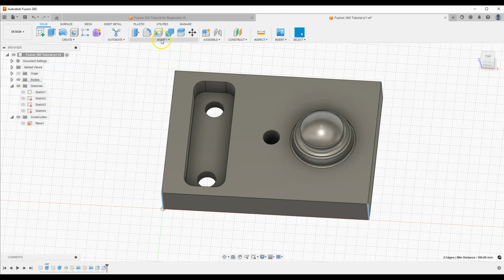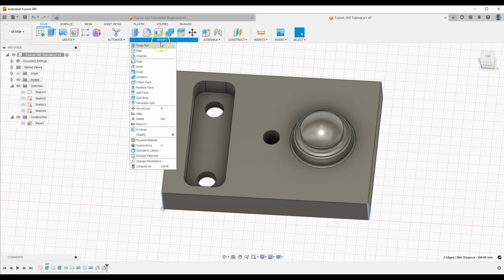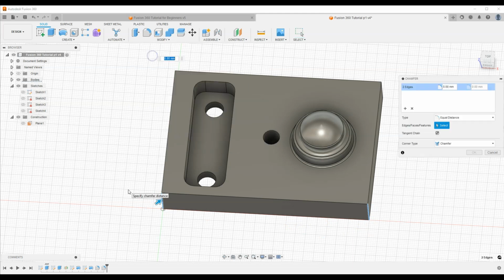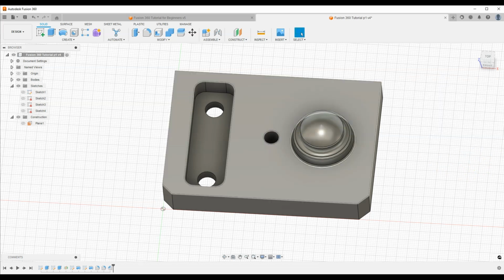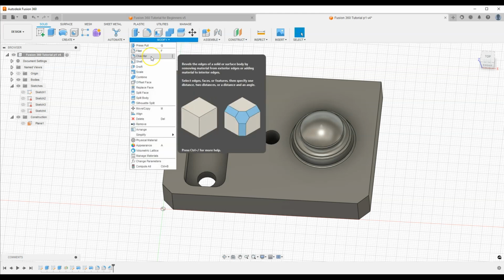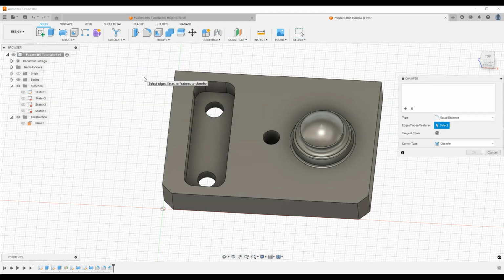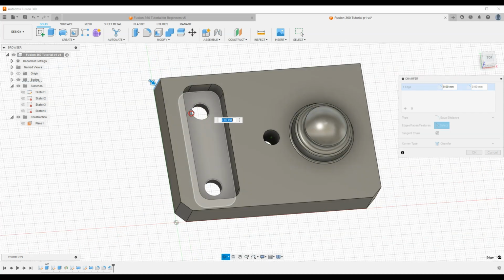And when it comes to adding chamfers, we do it in the same way as adding rounding. That is, first we select the edges that we want to chamfer, select the chamfer operation and determine the size of the chamfer. We can do it by dragging the arrow, or we can specify the value in this place, and I enter 5 mm here and click OK. Or as in the case of adding roundings, here we can also first select the chamfer operation and then select the edges that we want to chamfer.